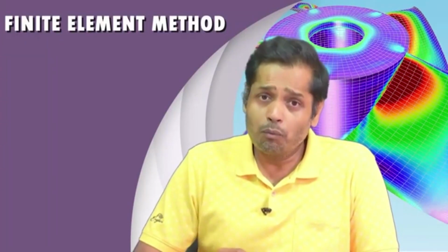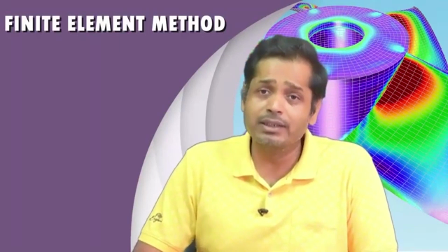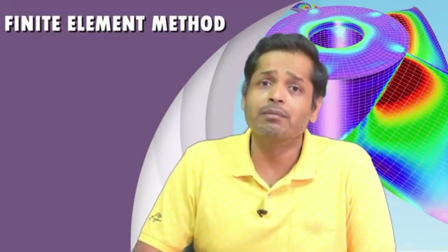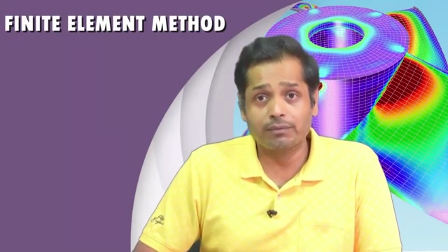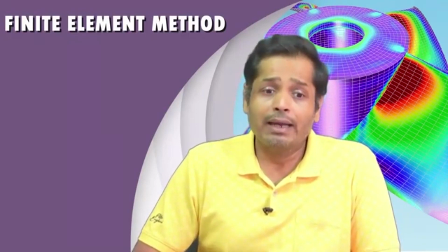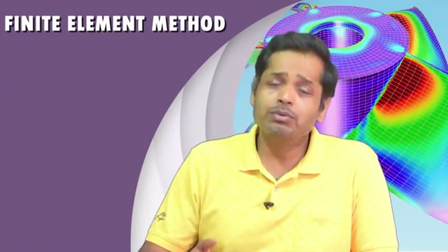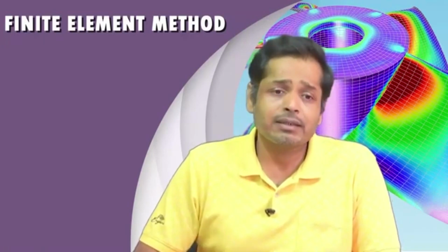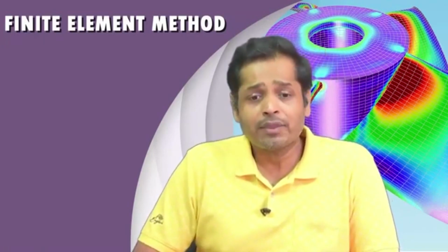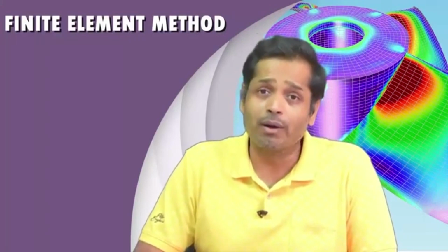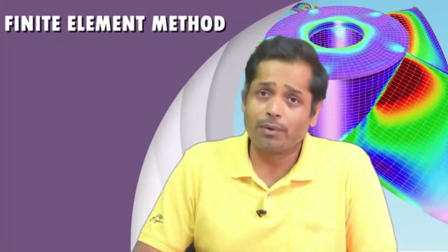Here, when we invoke the interpolation condition, it is the interpolation of the primary variable that is important for us. And through that, the shape function we get, we had seen in the last class again, gives us global continuity of the shape function approximation of C0, which is the minimum requirement for a finite element approximation.